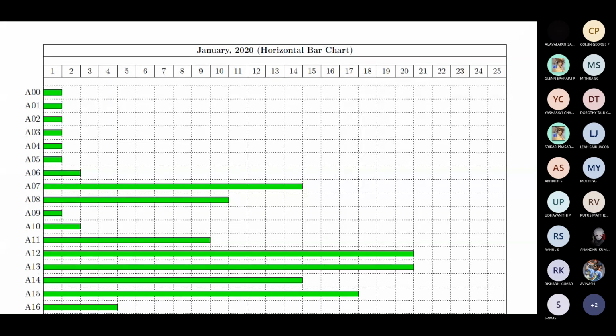And the advantage of that particular method is it will sequence activities based on the occurrence. Right? So this is just a bar graph. What Henry L. Gantt has done is sequence them based on the occurrence. Like we know that this is A00 site clearance. Unless we clear the site, we cannot start the other activities like site surveying or site marking or even excavation, right? So he has made that into a sequence, right?